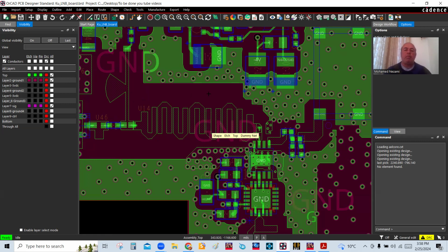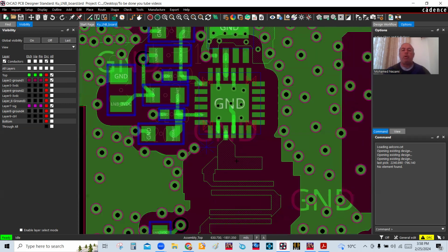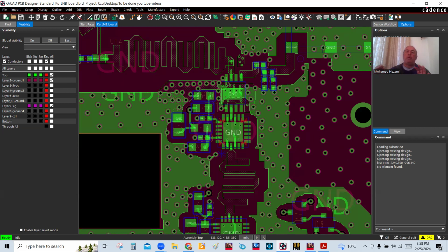So we wanted to make sure that the performance did not get corrupted along the way while we transferred the image of microstrip work from these packages using either transformation via DXF or some other way of doing it, that we took this into a Cadence library, and then we use the Cadence library symbols of footprints as footprints.